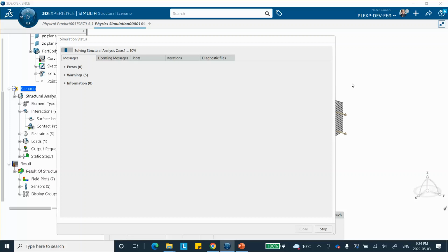There's an icon there. You can click on it, and it flips the arrows. But I could not get it to do that for the analytical rigid surface. That's why, if it cuts through, I'll go back and flip the direction of the arrow with that flip direction checkbox there.